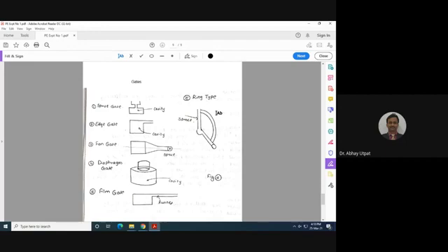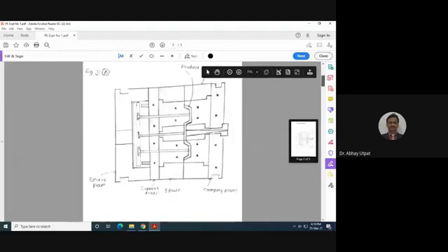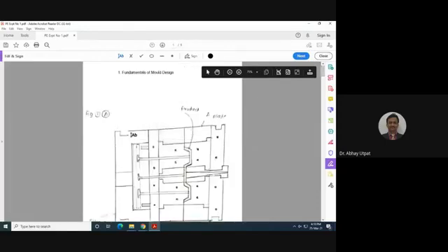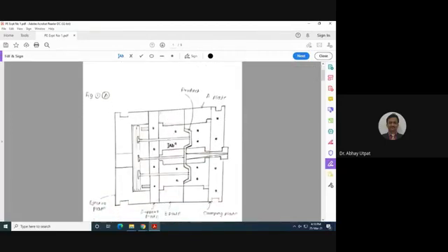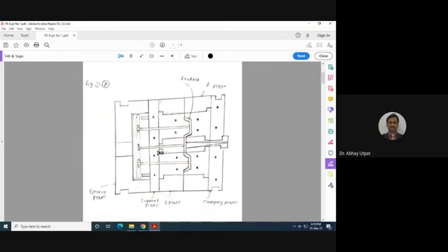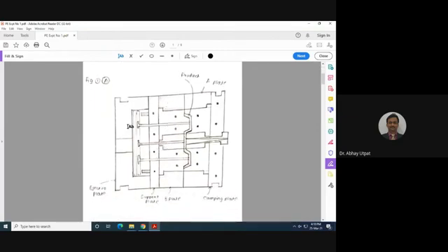Let us take the review in short. In today's fundamentals of mold design, what we have covered? We have covered the process of opening and closing of the mold and making of one simple component using there is operation of mold, operation of injection mold. How complicated the injection mold is, just don't see only cavity. Along with it, it carries heating, cooling arrangement, it carries clamping arrangement, it carries ejector pin arrangement. That's why injection molding process is, even you are getting, it is fast process, but there are a huge number of steps are involved into it.